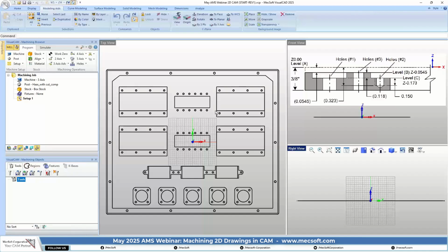And the check surface is just simply the mesh or the surface that you don't want the tool to violate. So that's pretty straightforward if you have a 3D surface model. If you only have a mesh model, then you need to add your drive surface. Typically, you can just put a cylinder inside your mesh, and you can use that cylinder to orient the spindle, and then it won't violate the mesh if you define it as a check surface.